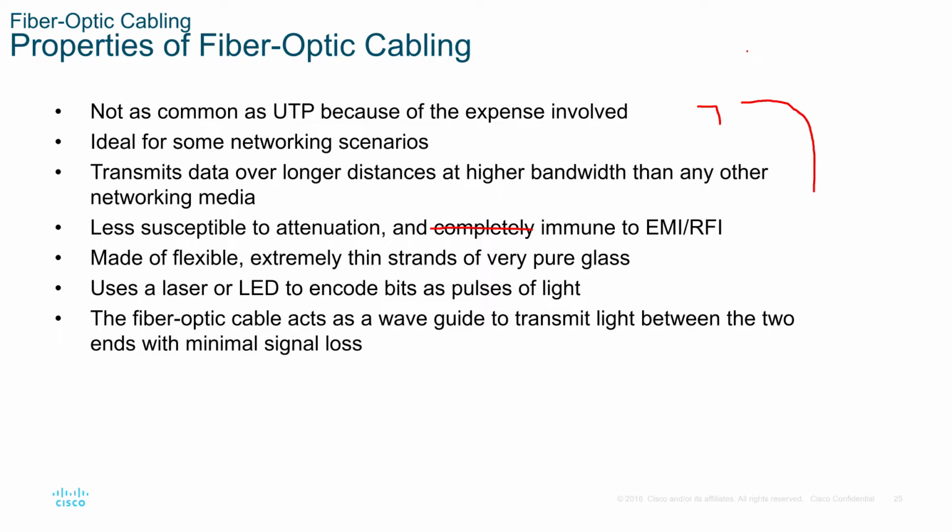Now, as we mentioned those, you never ever look into the end of a fiber optic cable. Whether it uses a laser or an LED, the light will do damage to your eyes. Cards are made that you can shine the light onto the card to see if it's actually transmitting.